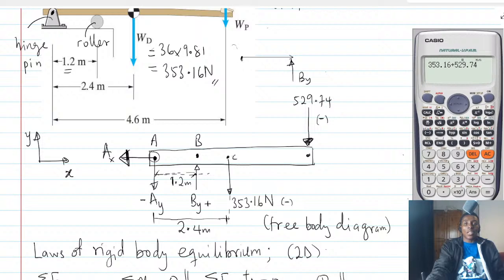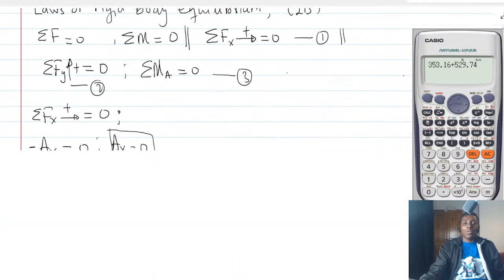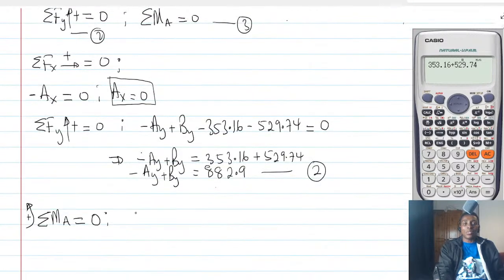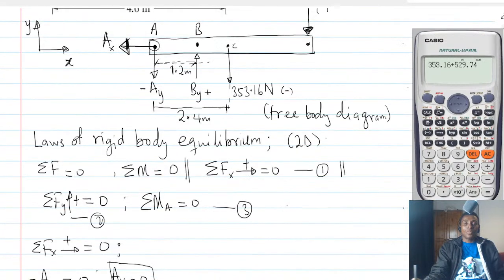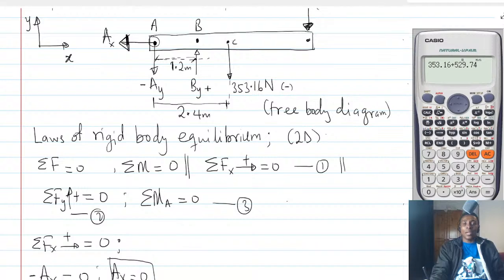What is going to happen if you fix this point? You realize that this rod, if I apply a force in this direction, is going to go in that sense, right? So basically that is going to be counterclockwise. So 1.2 By, which is actually positive. So we are done with By.